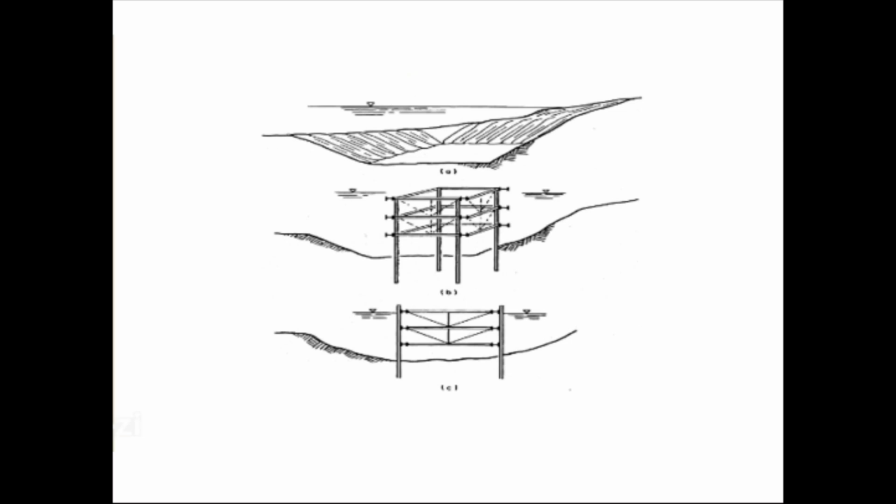Figure A, for a typical cofferdam such as for a bridge pier, the construction procedure follows the listed pattern. Pre-dredge to remove soil or soft sediments. Figure B, drive temporary support piles.